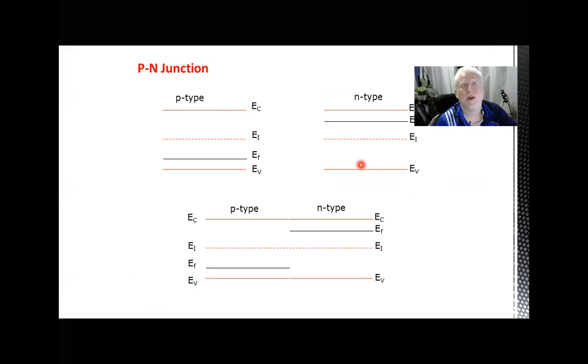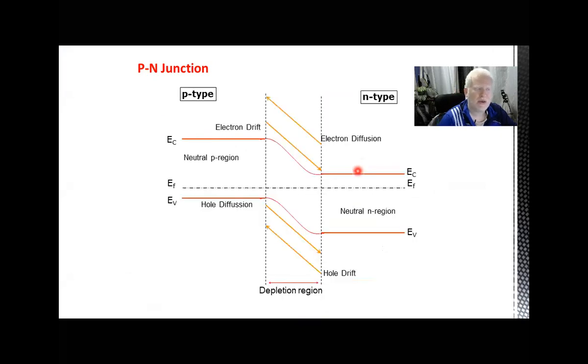Herein, we find that we need what's called a reference. Our reference was the E Fermi, because the Fermi level is the level at which the probability to find an electron is equal to half everywhere. So we plot the n-type portion and the p-type portion with respect to the Fermi level, as you can see in the slide.